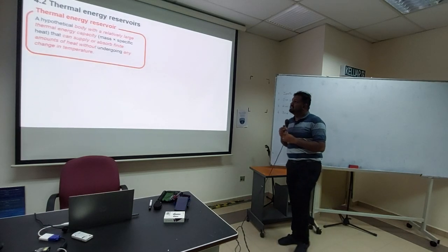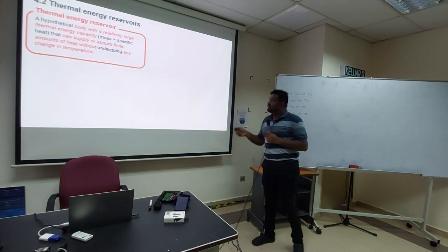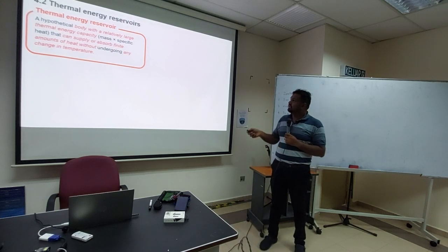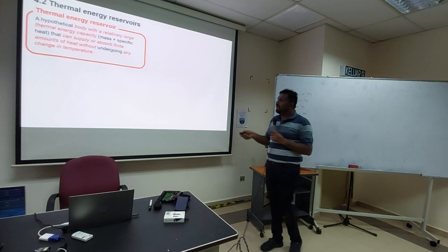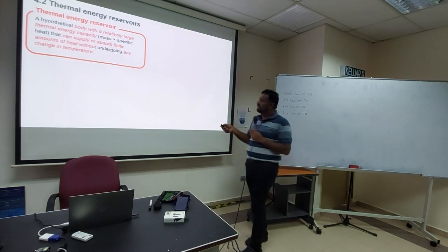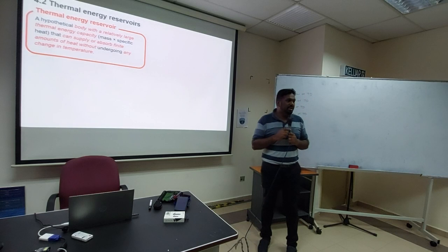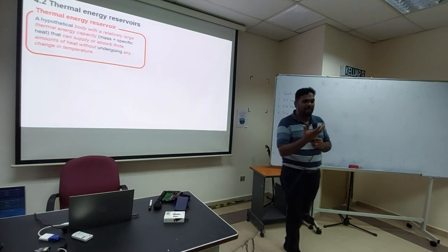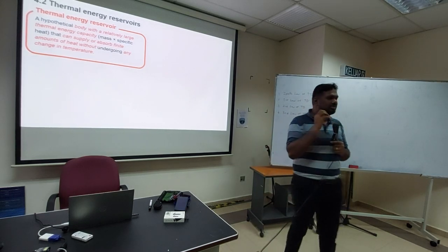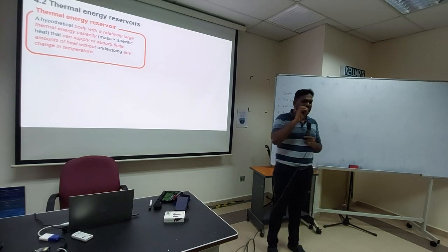Okay, so we will see about thermal energy reservoir. Okay, what is a reservoir? A hypothetical body with a relatively large thermal energy capacity, so mass and specific heat, that can supply or absorb a finite amount of heat without undergoing any changes in temperature. So meaning, it's like a power bank. Imagine a power bank. You can put a lot of battery. You can charge. You can keep on charging.